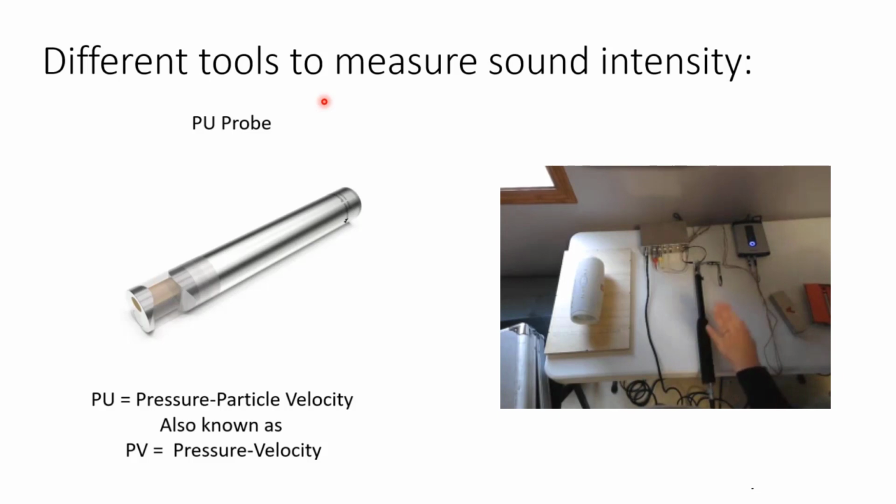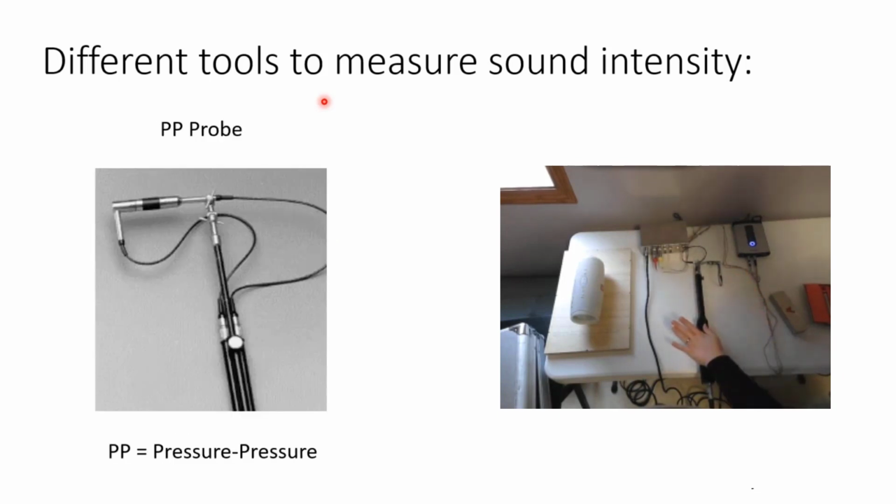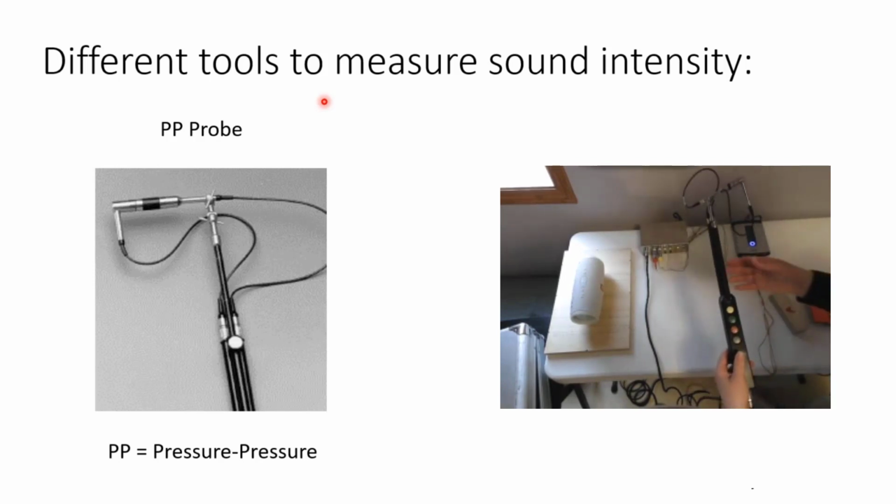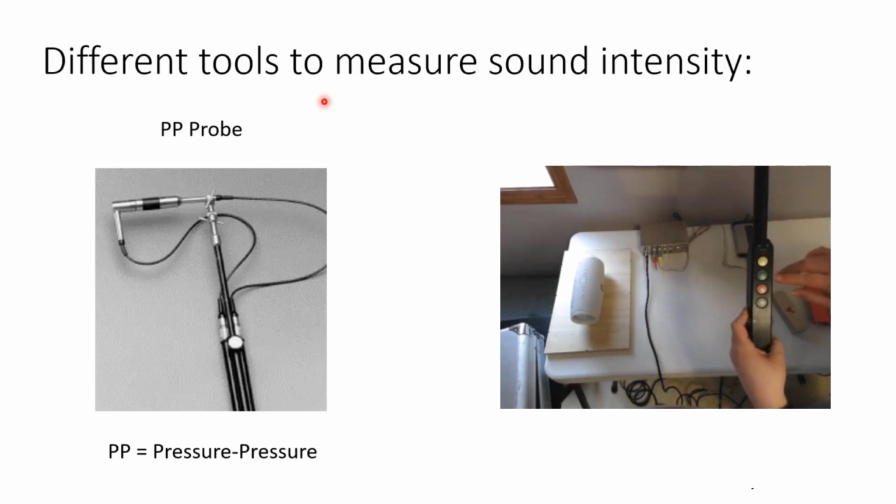And then I've got my sound intensity probe that's also connected to my Scadas XS. This one also has two channels for both microphones. This one's nice. It's got a lot of fun buttons. If you're measuring a lot of points in a lab, this is a little remote that can help you skip through menus on TestLab and make your testing a little more efficient. So if you're looking for that, this might be something for you.